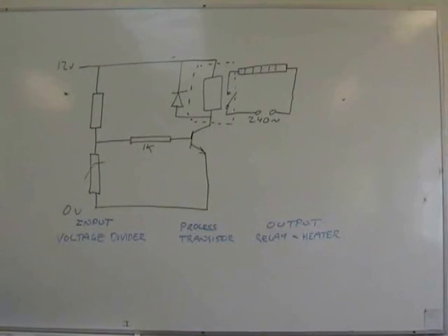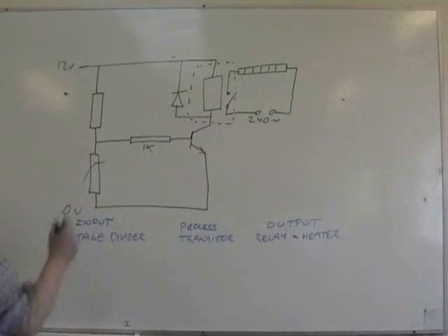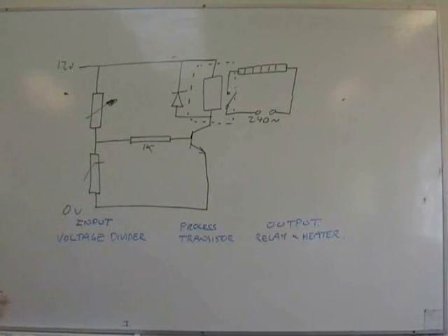Here we have a transistor control circuit. It's measuring the temperature, and in the cold it's switched on here. If that's a variable resistor, you can change the point at which the transistor switches on. Okay, right, how does it work?